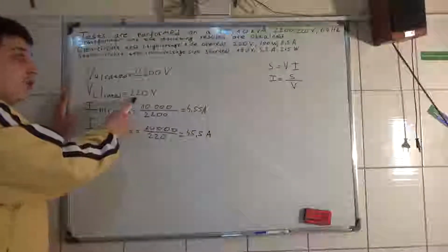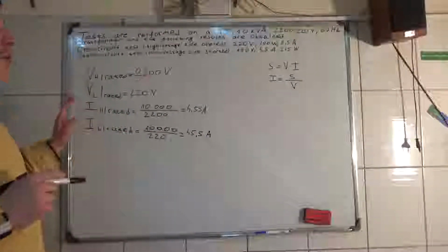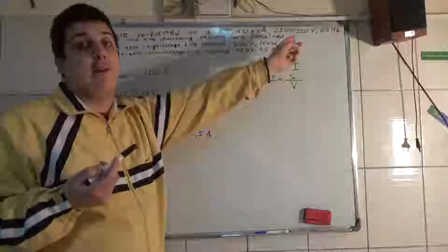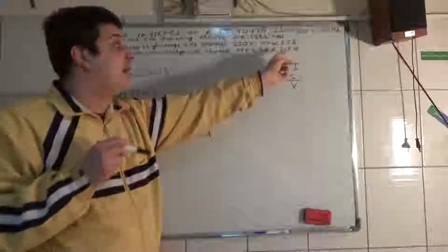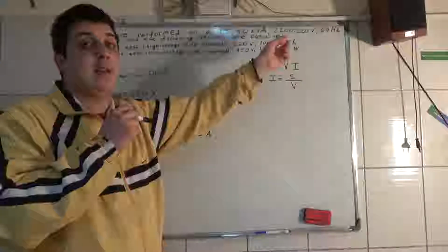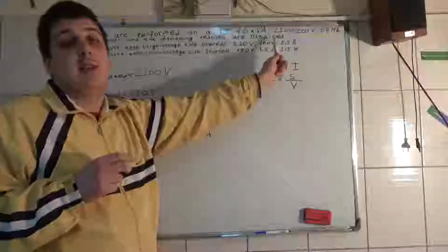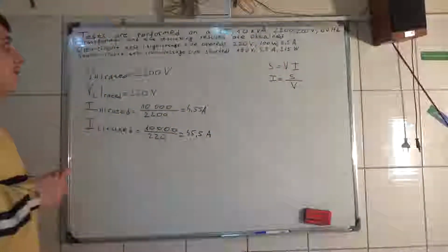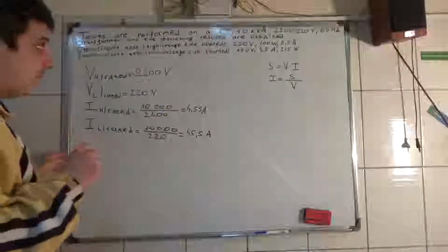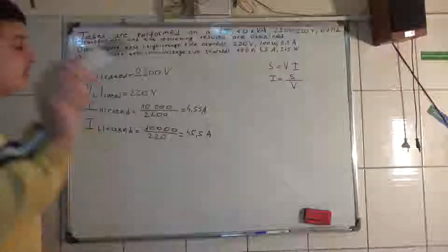As you can see, 220 volts. And why is the current less, 2.5 amperes? Because in an open circuit test, you only have an exciting current. So this here on an open circuit test is the exciting current of the transformer, but you will see that later.